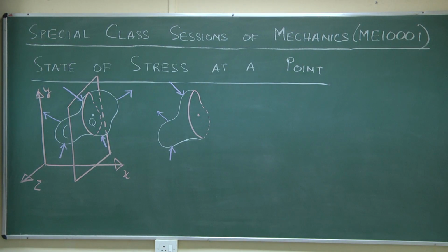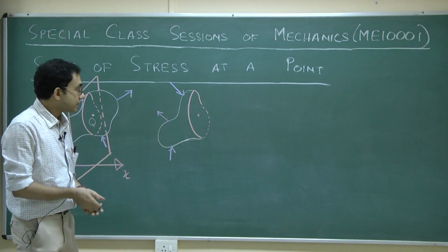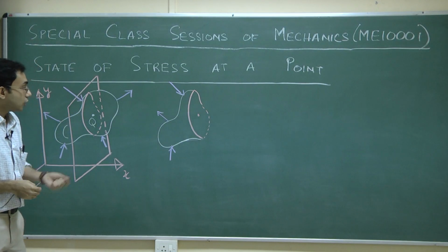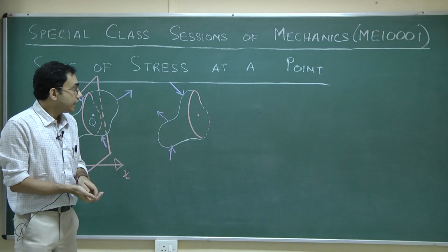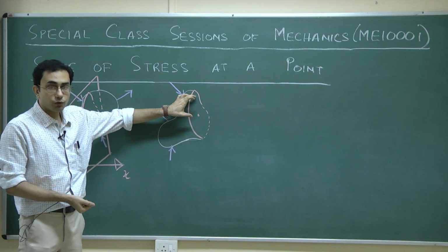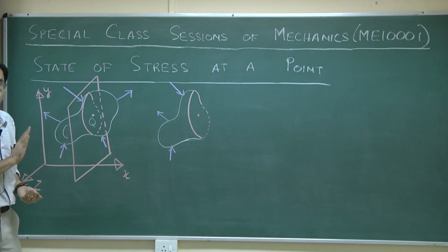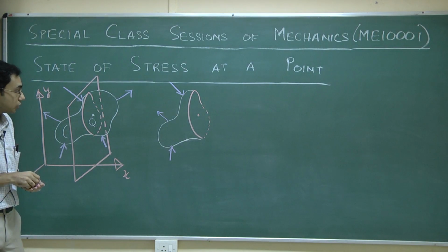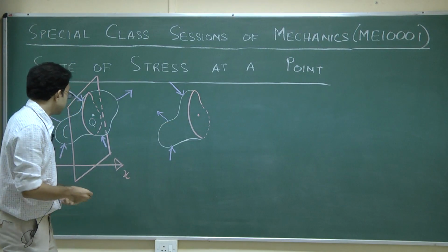Alright. Now, when we expose this surface, if to begin with this entire three-dimensional body was in static equilibrium, this portion as I have drawn it will no longer be in static equilibrium. So, in order to have the static equilibrium maintained, I would necessarily have a distribution of forces present on this exposed surface. Now, I do not want to depict all of that. What I want to do is focus my attention entirely on this point Q.